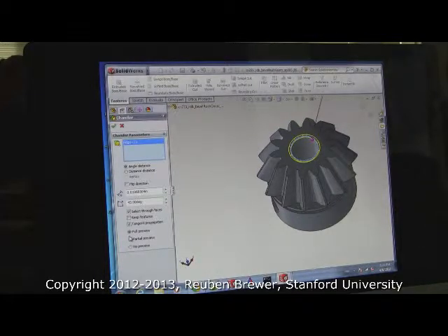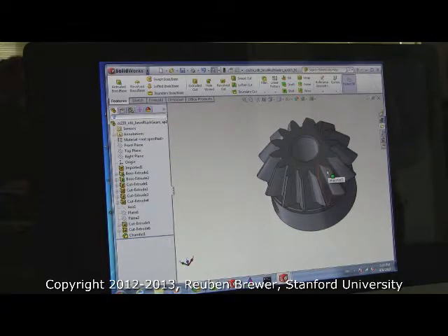So here's the thing. If this were machined out of metal and you were sending this to a shop, you'll want to use a chamfer because they have special tools for chamfering, so it's super easy and cheap. We're 3D printing this one, and the 3D printer does better with smooth edges versus sharp. So instead of doing a chamfer, we're going to do a round. Go ahead and click the check mark just so you see what it looks like. See it? Okay. Now just go ahead and delete that chamfer. I just wanted to show you that's how you do a chamfer.